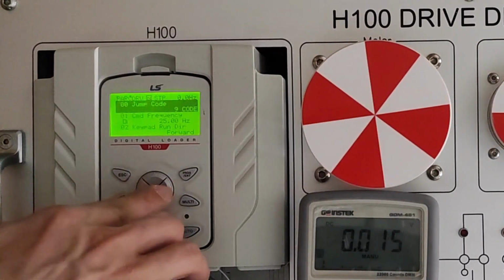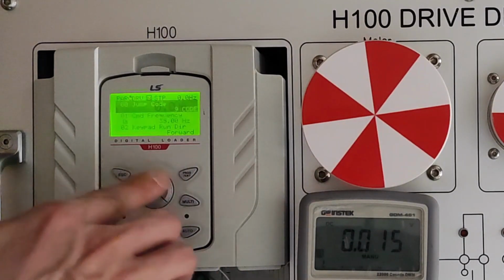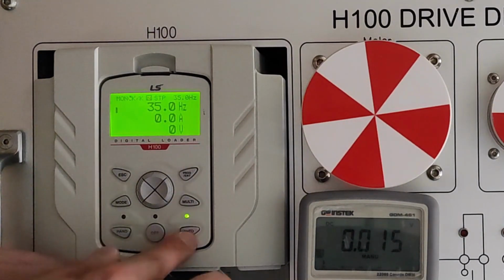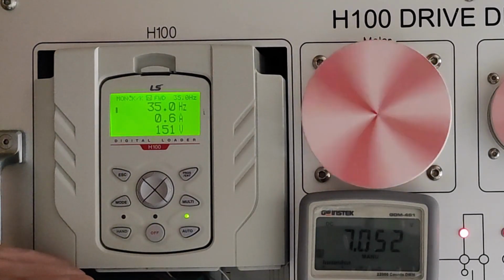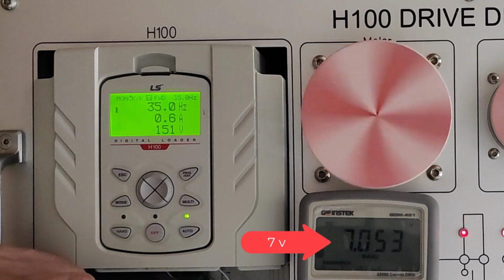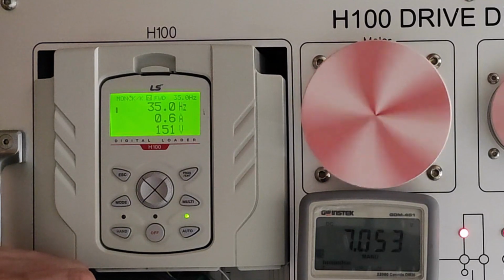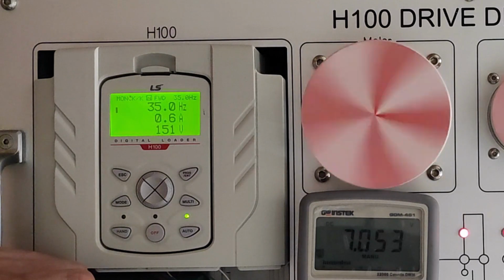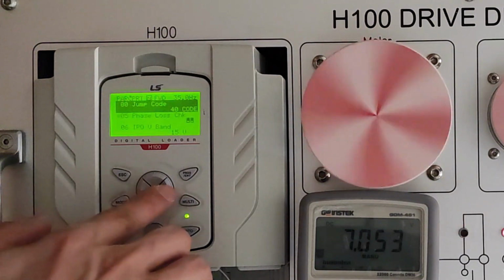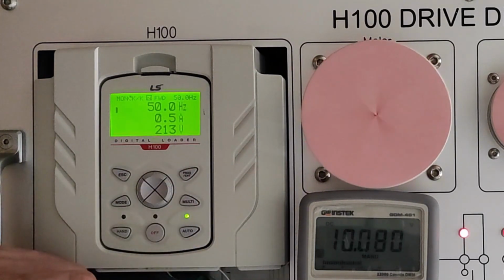Now again, for example, I'll set a frequency. I set it to 35 Hz and restart the inverter. You can see that the output voltage is changing, and right now it's giving me 7 VDC at the output. I used the AO1 and CM terminals and I set the DIP switch for the AO1 terminal to VO. That is, now my output is based on a voltage from 0 to 10 volts. I'm setting the maximum frequency again, so at 50 Hz it should again display 10 volts on the output,